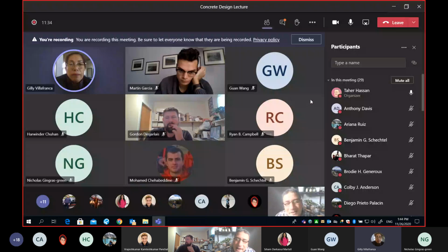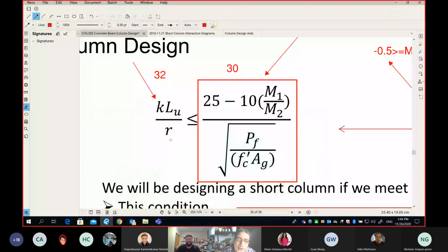Are the guys following? I'm trying to mislead you, okay? I'm saying here, we make our beams so strong. We fill our beams with lots of rebar, and we make the connection very strong, so it can restrain rotation, which means I go from K equal to 1 to K equal to, let's say, 0.6 or 0.7, okay?